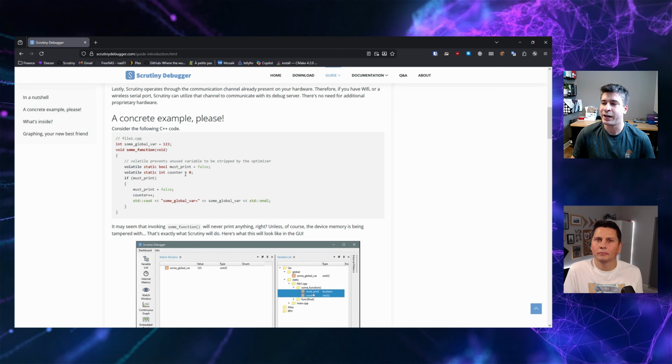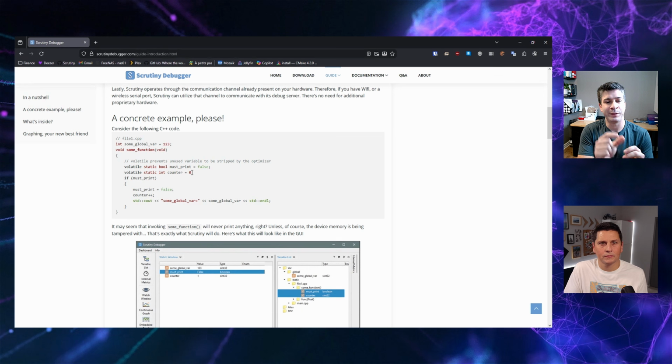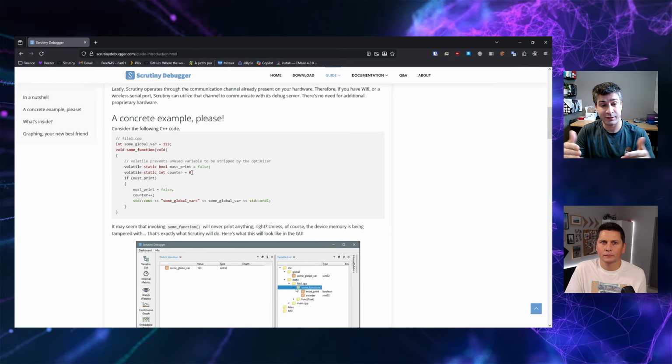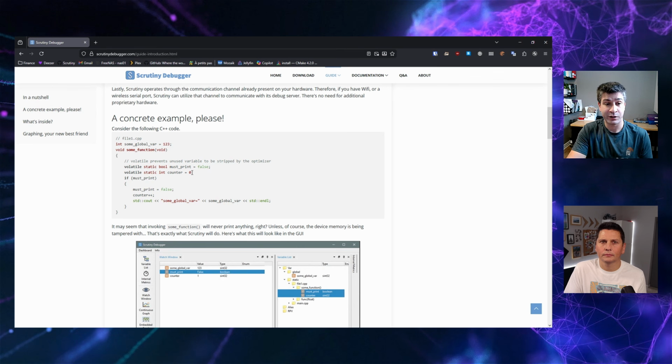then do something. But that will never happen because it's always false. But if you have a piece of software, a piece of code in your firmware that is allowed to modify any piece of memory, then you can make that true from the external world. Right? And that's what Scrutiny will do. You put a little piece of firmware that will accept to do memory dump or write the memory. So it exposes your whole internal memory, and a software from the external world that knows the memory mapping of the firmware using the debugging symbols can send a command, all right, write the memory address at that location to this value, and then boom, it affects the